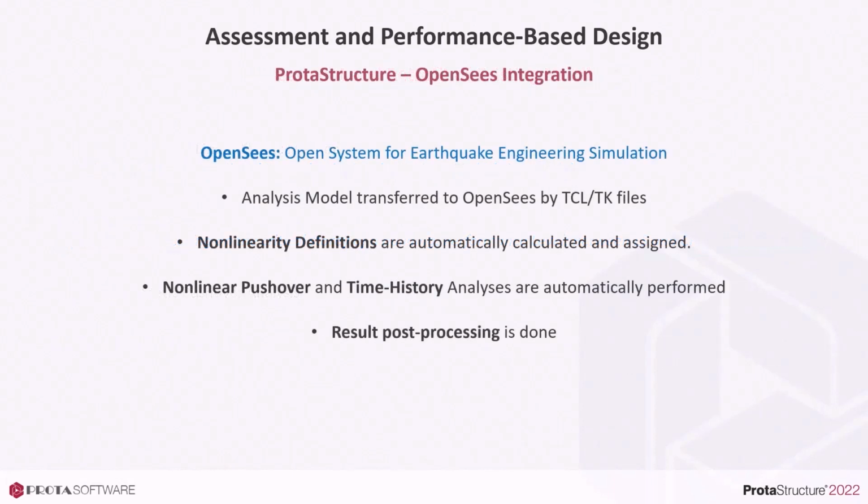One of the strengths of ProtaStructure resides in the ability to conduct nonlinear pushover and time history analysis for assessment and performance-based design of buildings. We achieve this by OpenSees integration. OpenSees is an open-source software framework for simulating the seismic response of structural and geotechnical systems. OpenSees has advanced capabilities for modeling and analyzing the nonlinear response using a wide range of material models, elements, and solution algorithms. Nonlinear analysis requires a wide range of algorithms and solution methods. OpenSees provides nonlinear static and dynamic methods, equation solvers, and methods for handling constraints.